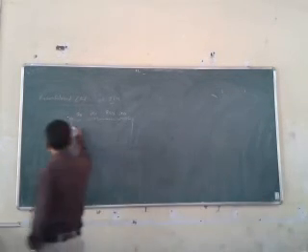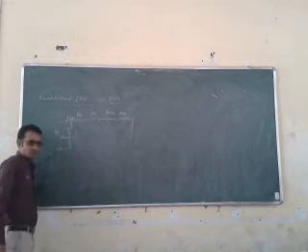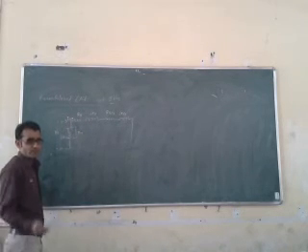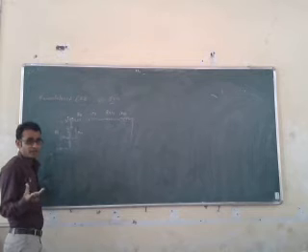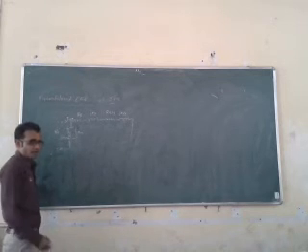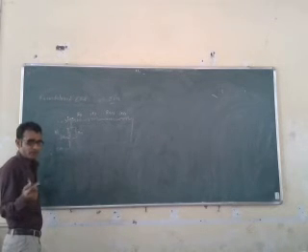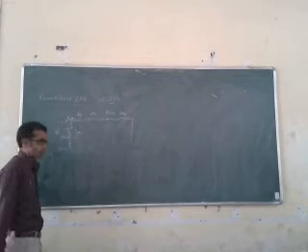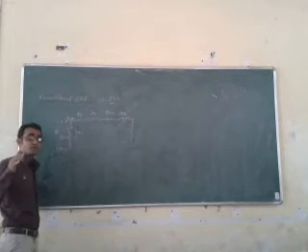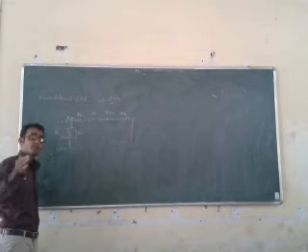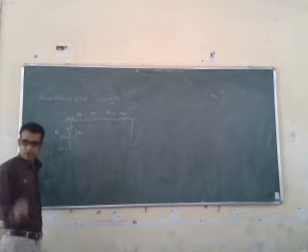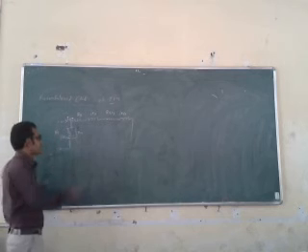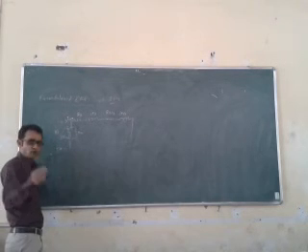Along with this, there is one resistance, that is RM, the resistance which is responsible for creating core losses when the transformer or the machine is on. If there is a flow of current through a particular core, then there are some core losses. I hope you get this. The losses in the core, and the resistance offered by that core, are the core losses.